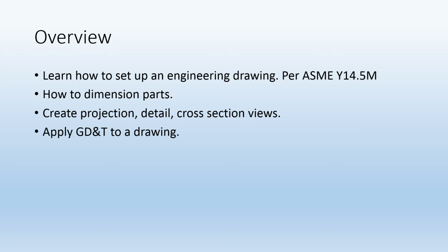So we'll set the engineering drawings per ASME Y14.5M, that's the American Society of Mechanical Engineers, and it's an update of ANSI, which is the older standards, and basically sets the premise for how you dimension a drawing, how you create views and properly dimension them. It's a standard that we all follow to make sure we keep consistency throughout our parts.